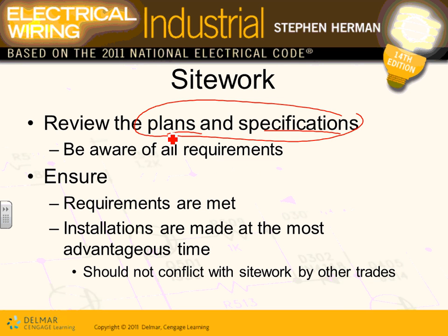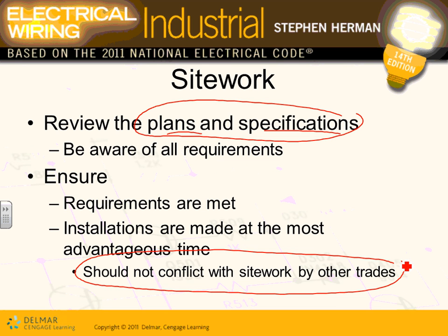You have to make sure that coordination with other disciplines is done, the elevation is okay, and where the power and the utilities are indicated should not conflict with the site of other trades. So the most important thing, like I said, in the site or elsewhere, guys, is coordination with other disciplines and other trades, underground or above ground.